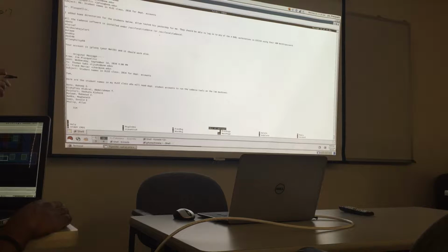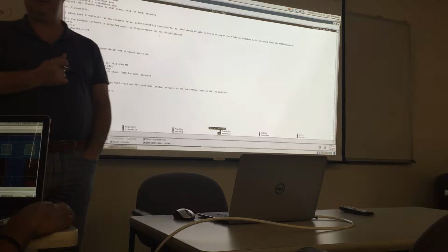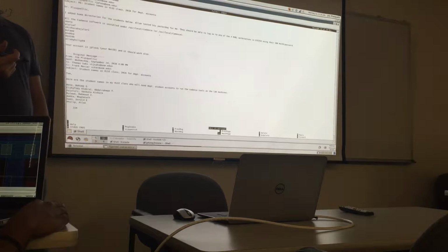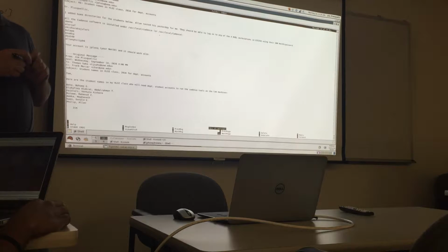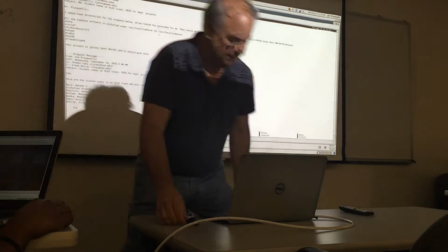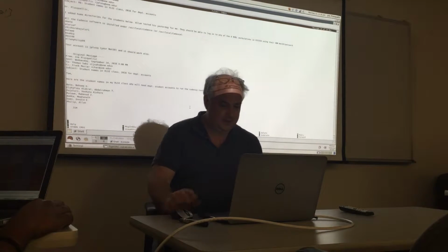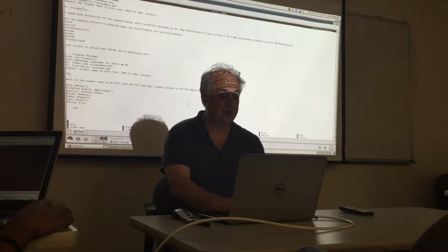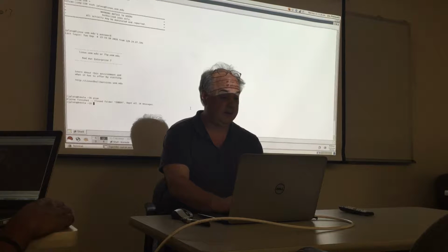To create it, have you guys created a pin? Do you know how to create a pin? Pins are a little tricky in Virtuoso. If you want to create your own pin, let me show you how. You can copy them, and that'll work, of course.